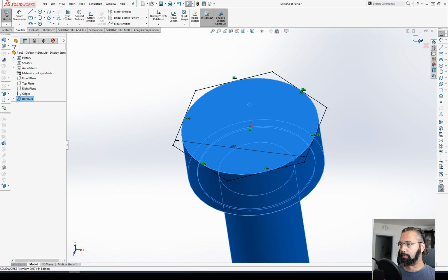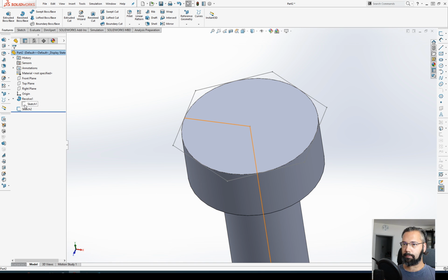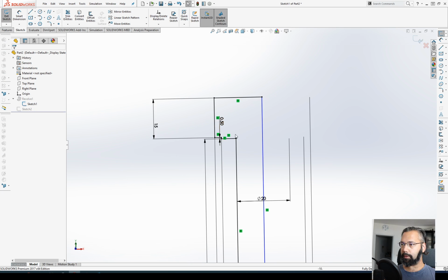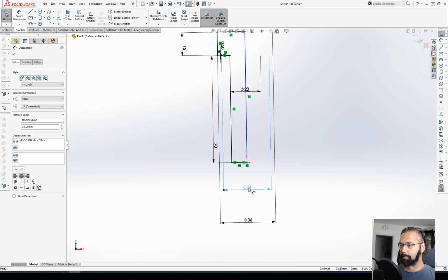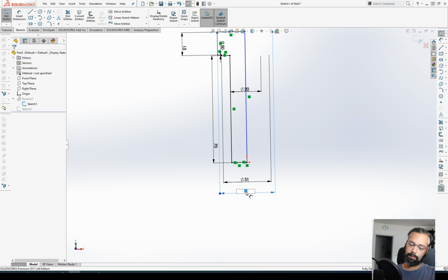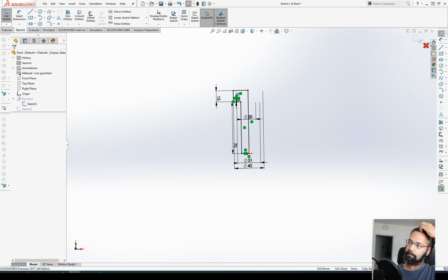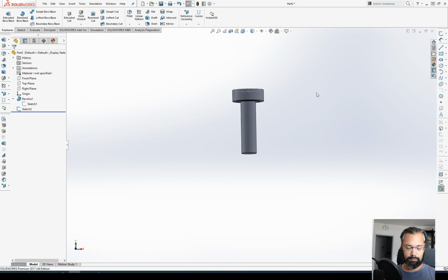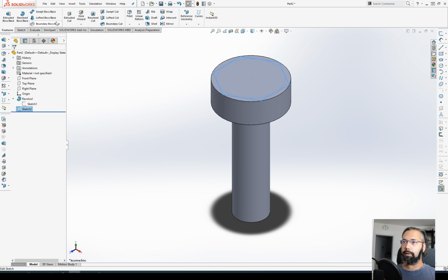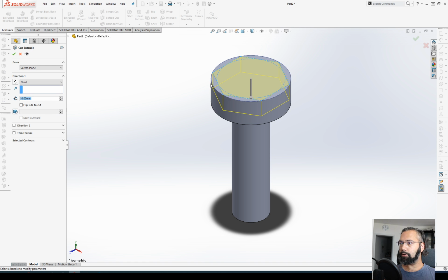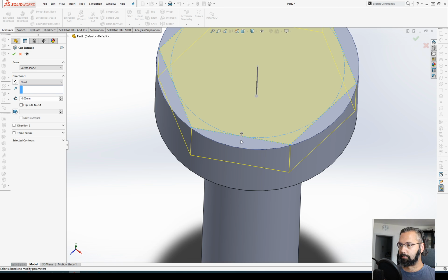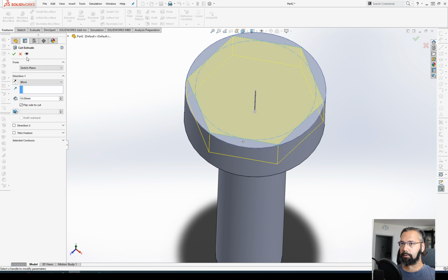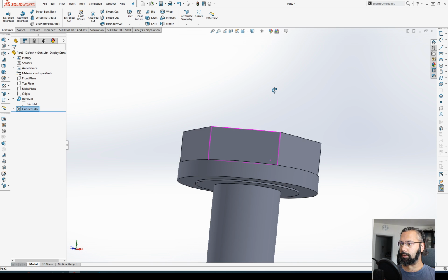And exit. Now you go back here, you need to define here 36. I already defined it as the cut thing, so let's take 40. Let's take 42. It's anyway going to get cut by the other one. So you click your sketch, you go cut, flip side to cut, because you see this little arrow. This cuts on the inside, this cuts on the outside. You go here, you say okay.